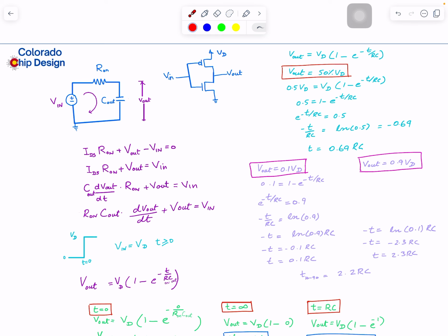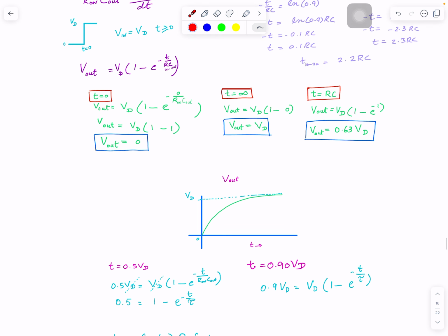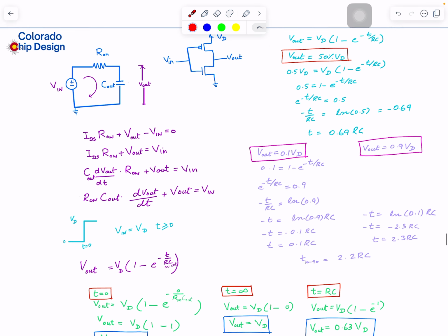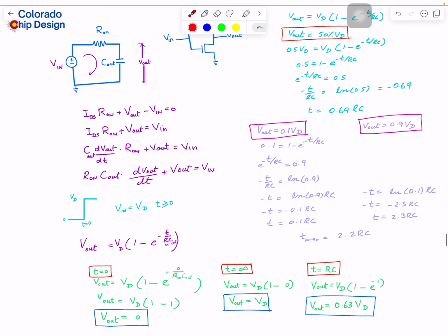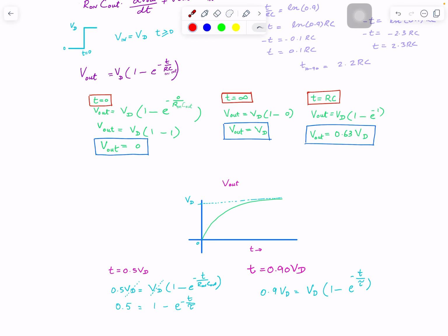Do I have a waveform? Yes. When you apply a step voltage at the input of the above circuit, the output voltage doesn't go sharply like that step. It takes a little bit of time. So what we really want to calculate in this case, and again this is a simplification of a real situation. The real situation will have a different delay, will not be a step, and the output will be even worse. But from this, at least we can derive an equation, which helps us approximate things.